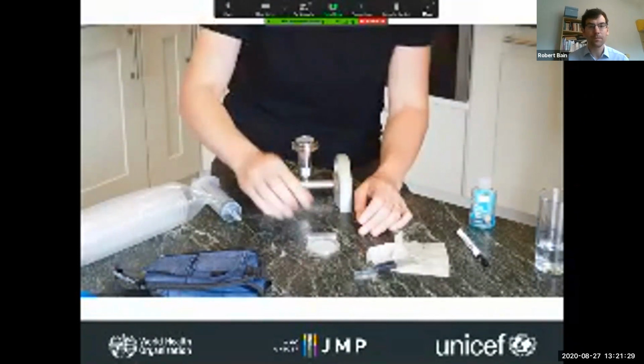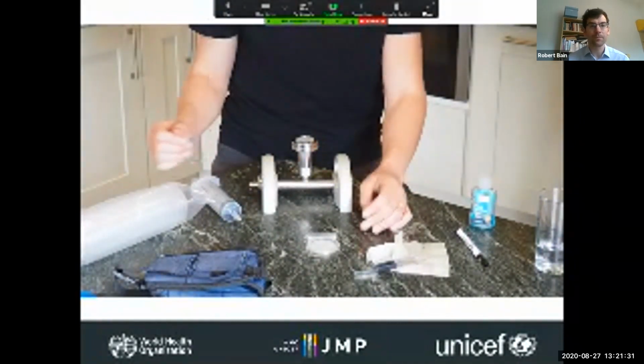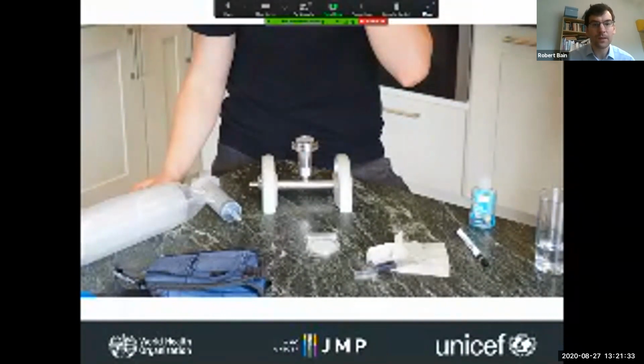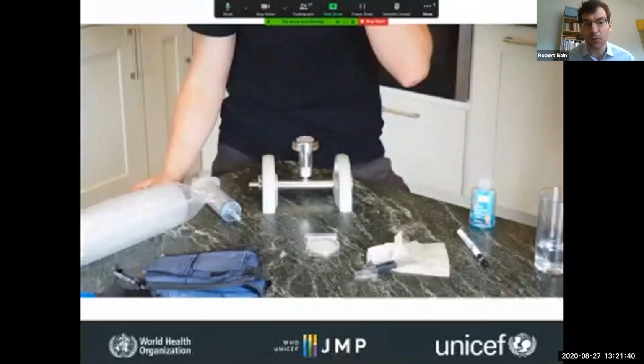The nutrient pad is now ready for incubation. Okay, so as you can see, it's a relatively quick test, but the field teams would be doing this once for the source sample, so the point of collection, and once for the glass in the household, and then for a subset of those households also doing a blank test. So they get a lot of practice with this.